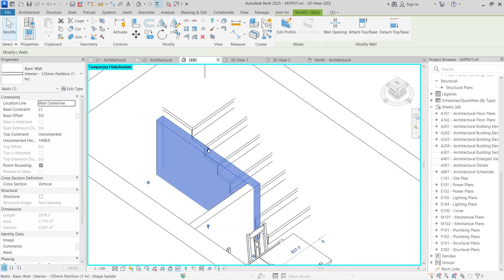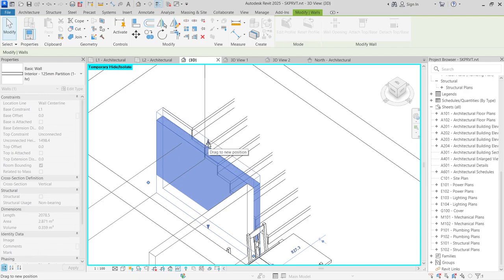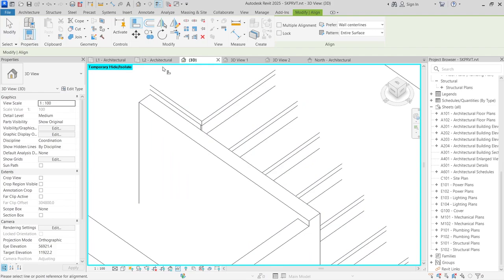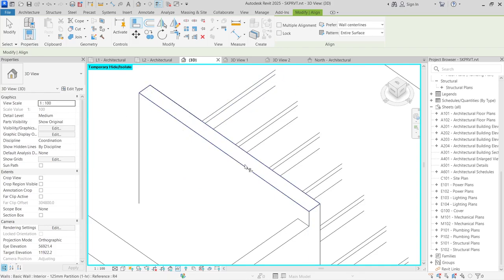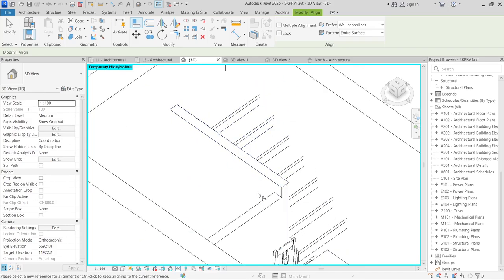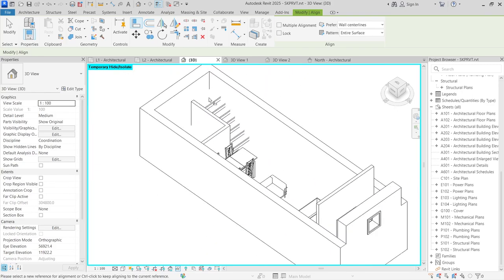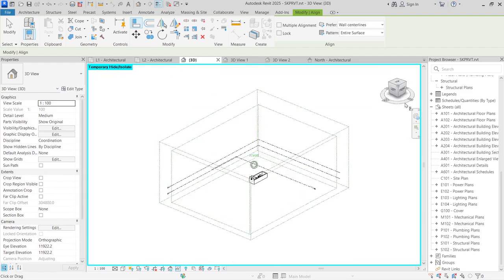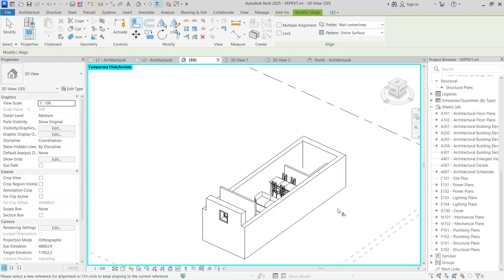So this staircase wall, I would want to bring this wall to meet with the staircase over here. I think I can use the align tool for this. So I can select align. I want to align this wall with it. So that's where it goes. So it's exactly where I want it to now. And then I also want to align this wall with this wall. So this is just using our view of Revit to make sure that our building is correct.